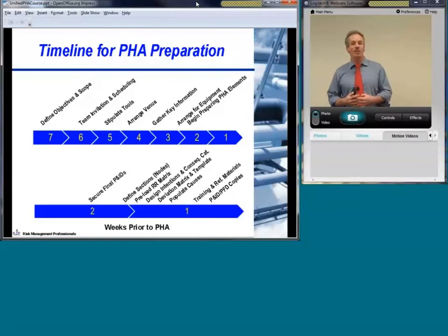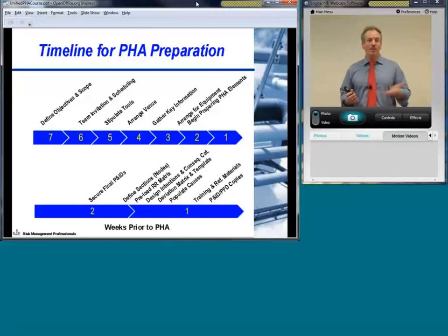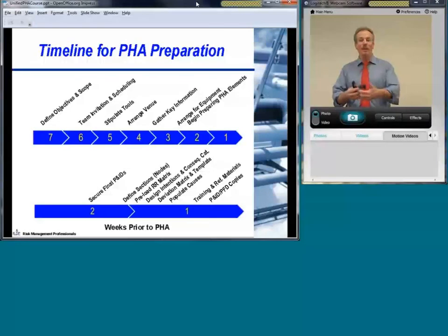At the bottom part of your screen, one of the final things that happens is you finally get, as a facilitator preparing for the HAZOP study, the final P&IDs, or the P&IDs that are going to be used for the HAZOP study. Once you get those, you can do the serious preparation in the last stage right before the HAZOP study: defining the nodes right beforehand, preloading the risk ranking matrix, making sure your design intentions and consequence categories are well defined, and binning various types of events as appropriate.